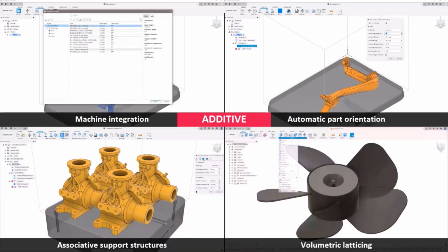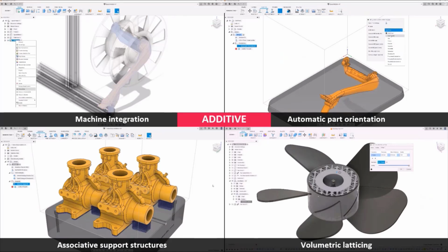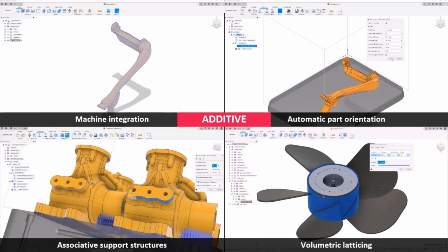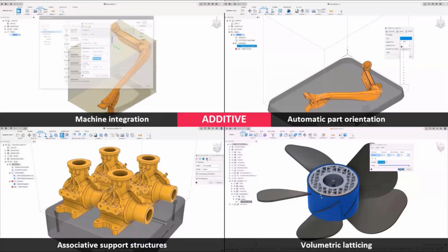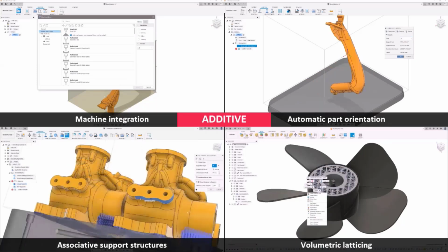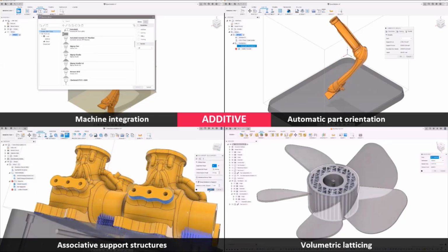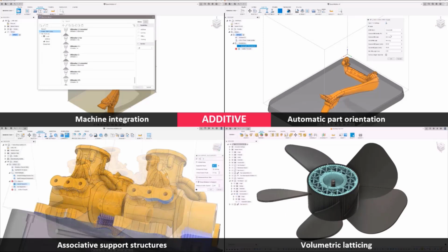When you want to hold the part at that position, you have to add a support structure. The system is going to decide the support structure for you. You just tell the system where you want to place the support, and after that, Fusion is going to calculate the support shape and number and size and how the support holds this part still.